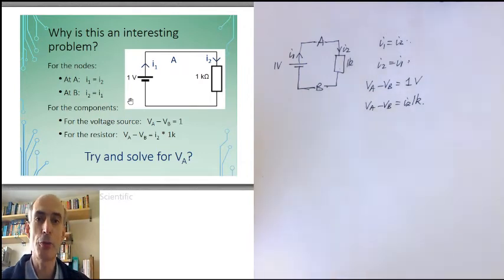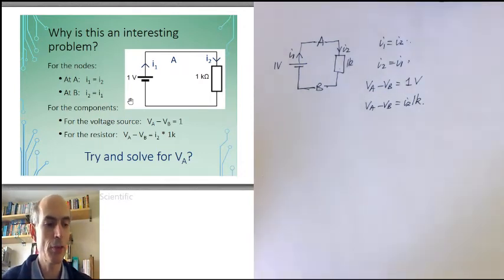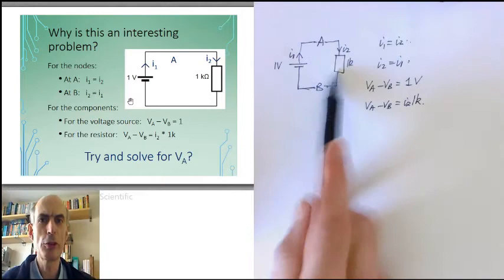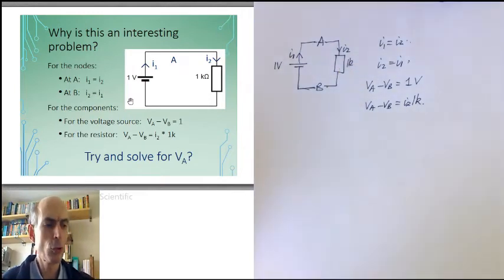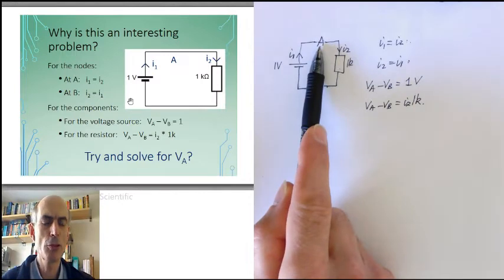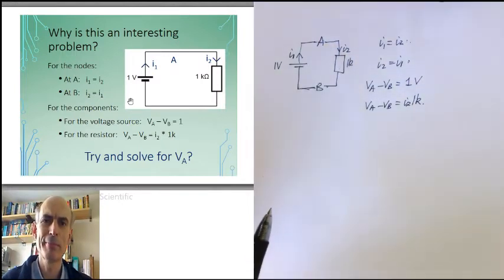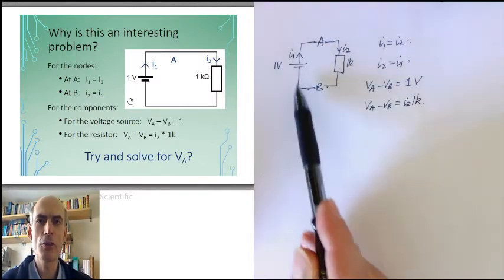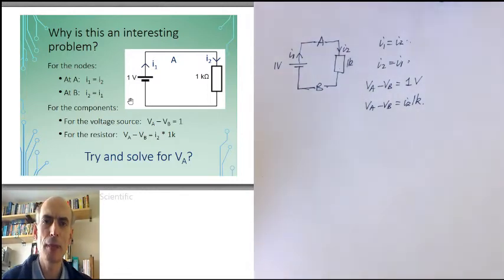The way round this problem is to notice that there is no voltage reference. You're trying to work out the potential at A, but relative to what? You don't know where 0 volts is. And 0 volts, ground, if it's not defined by a big stick being driven into the earth, is arbitrary.